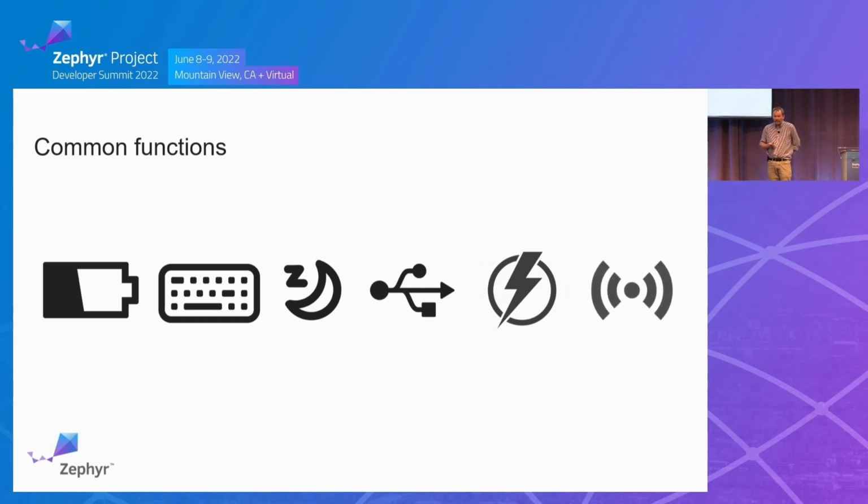And finally, we have the interface to the AP, the main CPU in the laptop. The EC receives instructions from the AP and reports the current state of all the above items so that the main operating system, such as Chrome OS or Windows, can act on them, for example showing a little low battery icon on the screen, or perhaps a message indicating that the laptop will shut down soon. So as I'm sure you can imagine, all of this takes a lot of software. It pretty much requires an RTOS with multiple tasks coordinating together.